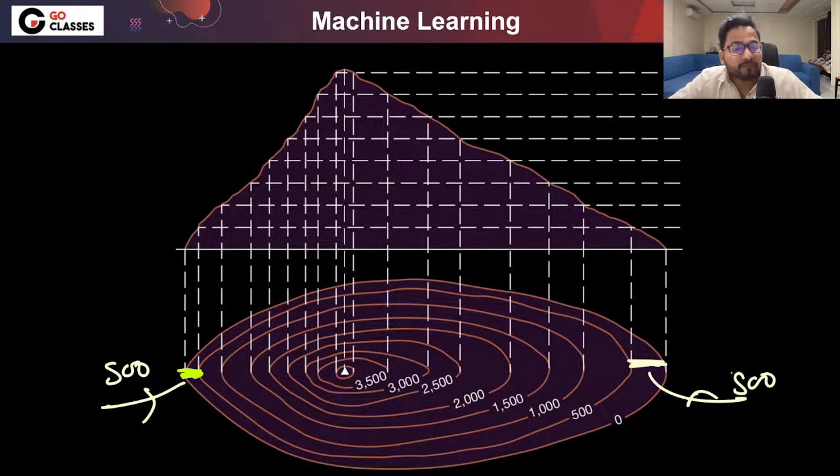Which means that at this particular point it is lazy, or very much horizontal type. It is not steep, not very inclined. But here the slope is steep. If the slope is steep, then the contours will be closer to each other. So by seeing whether they are close to each other, you can tell whether the slope is steep or not.